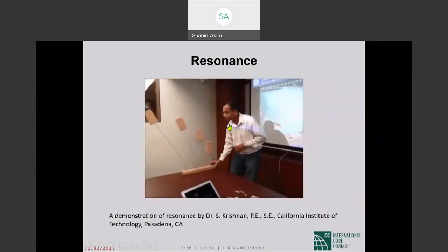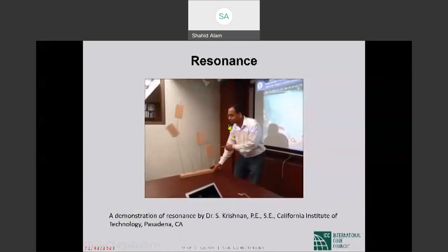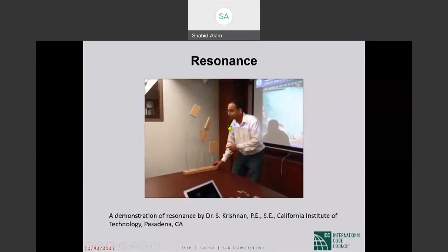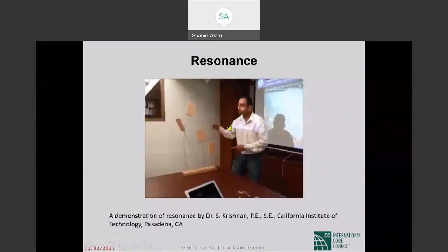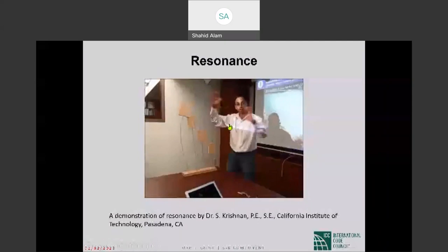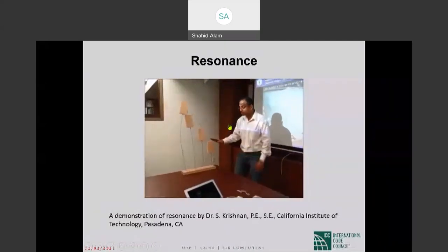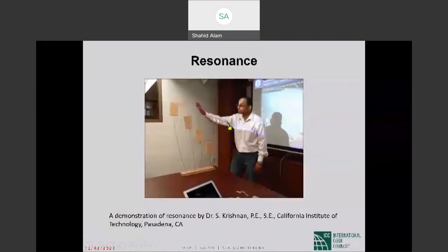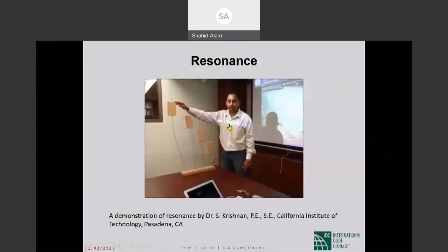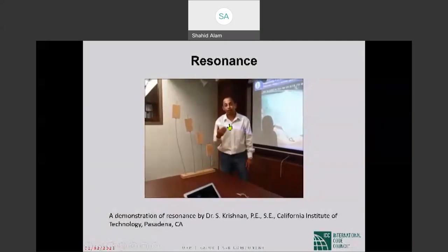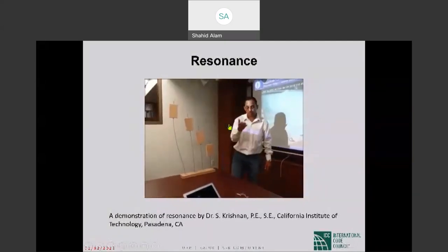Notice how the little house is just sitting where it is, whereas the tall buildings, or these long period structures, are going back and forth, getting a lot of response. Right? So the long period motion does not do anything to the low rise structure. It selectively excites our tall buildings. This is the difference between long period motions that you can see in a big earthquake versus high frequency motions.